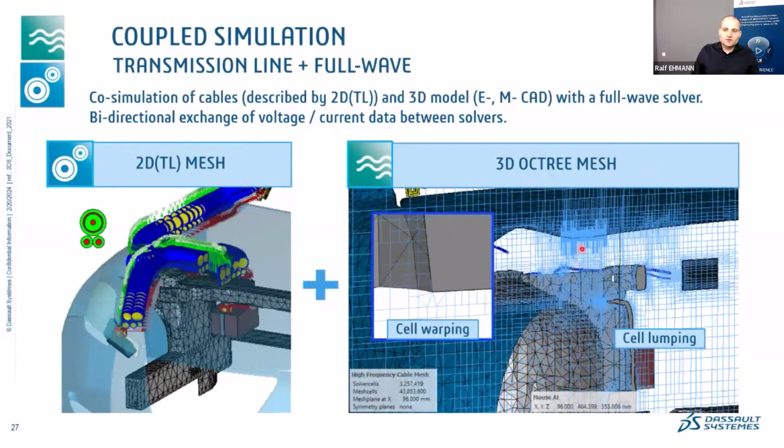And then the 3D solver takes the job and runs, evaluating how the fields propagate and how much they interact with other 3D systems. We are using the TLM solver here because we want to run the optimized time domain experience for you, and we want to use it with the meshing, here called octree meshing, where we use typical scenarios that help the discretized model represent the 3D better and more optimally.